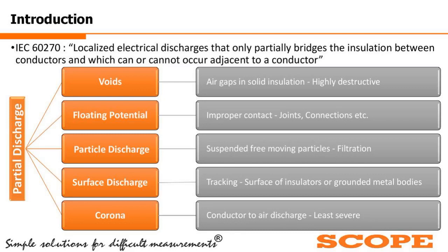Any foreign object remaining inside that insulation can create a void, and this void is going to create a potential difference or non-equipotential surface of the insulation.